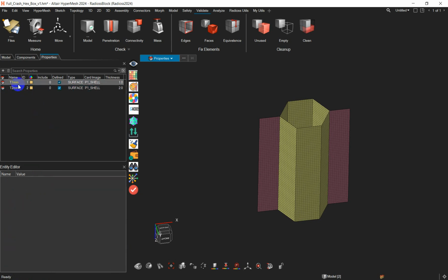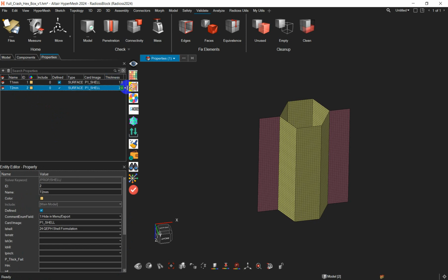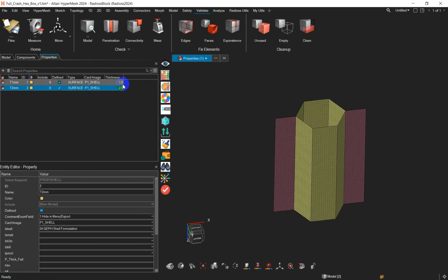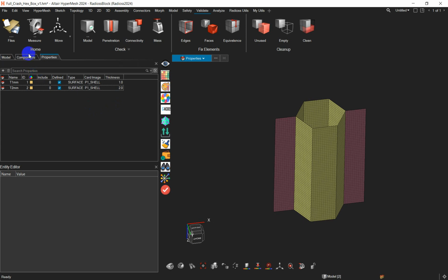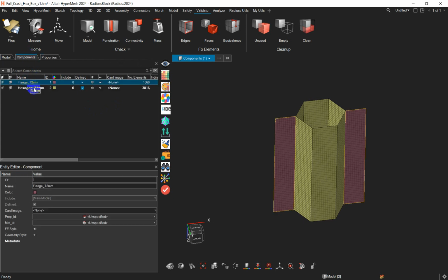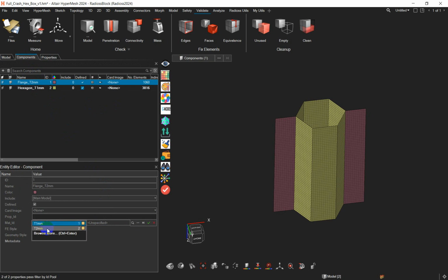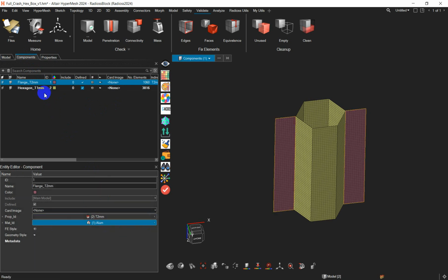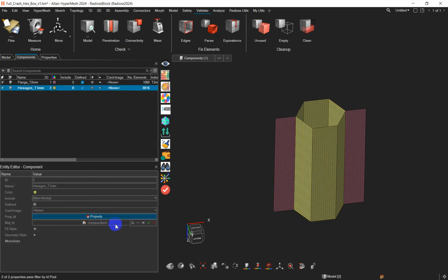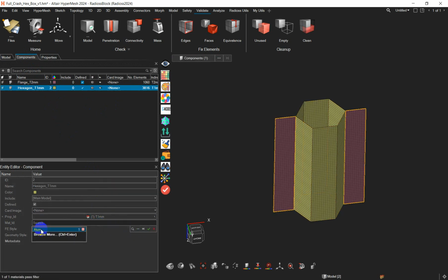Okay, so now we already have the thickness, so you can check again the thickness table here, which we can edit here is also possible. And next we can assign information for this part. I choose property 2 millimeters, aluminum. Okay, same. I choose this 1 millimeter and aluminum.